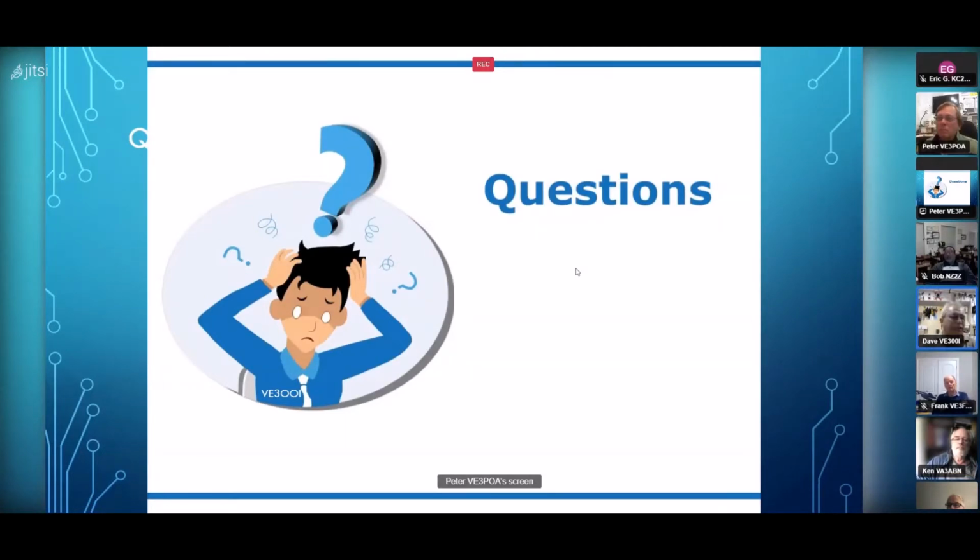Peter, a couple questions, if I can remember now. Yeah, I think 1 dB variation is nothing. I agree. Because given your experimental setup, Kevin's right, the board, you're milling it, the traces are not ideal. Like when Linear or whatever they're called now, Analog Devices, do these tests, their test boards have proper grounding, and all these vias tying the grounds together, and they've got strip lines, and they do everything in a very professional way.